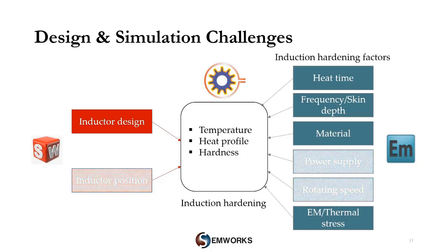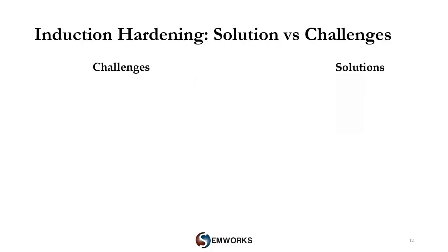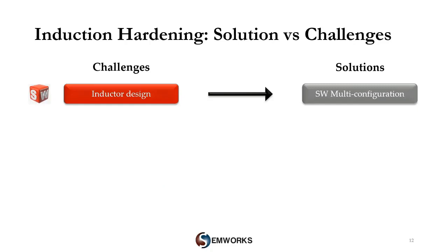All of those factors could be covered using EMS for SOLIDWORKS. But for today's webinar, we are going to focus on the highlighted aspects, in which SOLIDWORKS multi-configurations feature is used to vary the inductor design, as it is the most important factor that defines the heating profile and distribution.